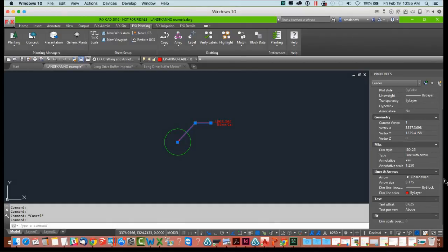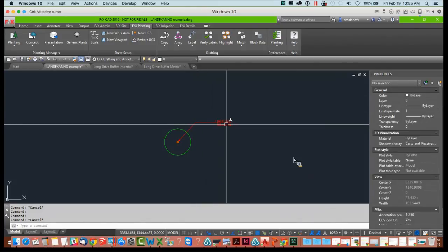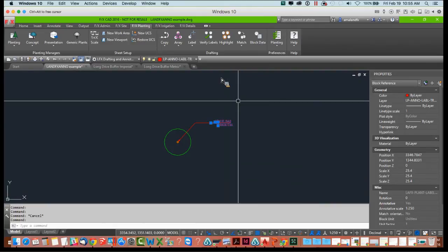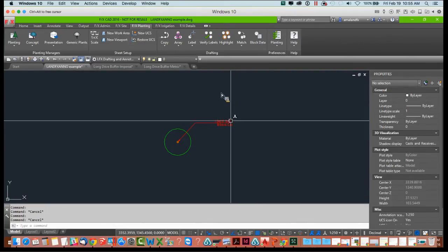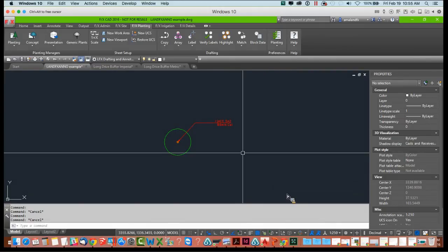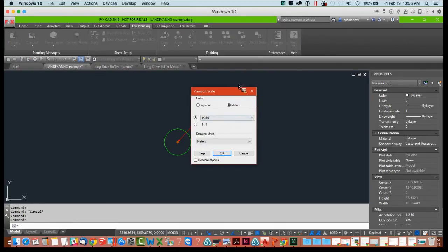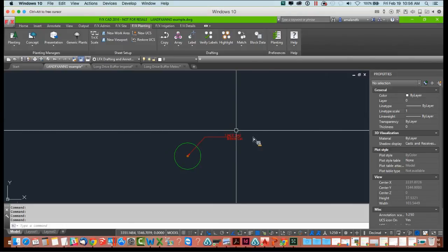Now I can turn off annotative. I can turn it off with this, and it's back, but I can't turn that off. It's grayed out for these callouts. So what you need to do is get rid of this if it's messing up, because most likely you're not using it correctly and you want to go back to just using this. So what I'm going to do is I'm going to turn Land F/X Anno off.